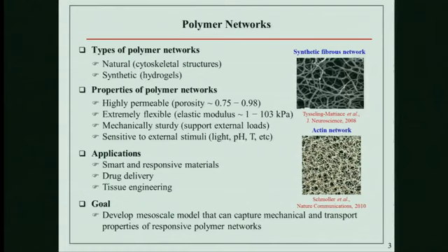Again, we have them in many different engineering systems. When we have these hydrogels, if we talk about transport properties, they are highly permeable. The porosity of these materials is large. It can be up to 98%, so it's almost entirely solvent, right? It can be maybe in the 70s at the low limit. At the same time, they are very elastic, right? We can stretch them hundreds of percent. They can be deformable, and they can still support mechanical load.